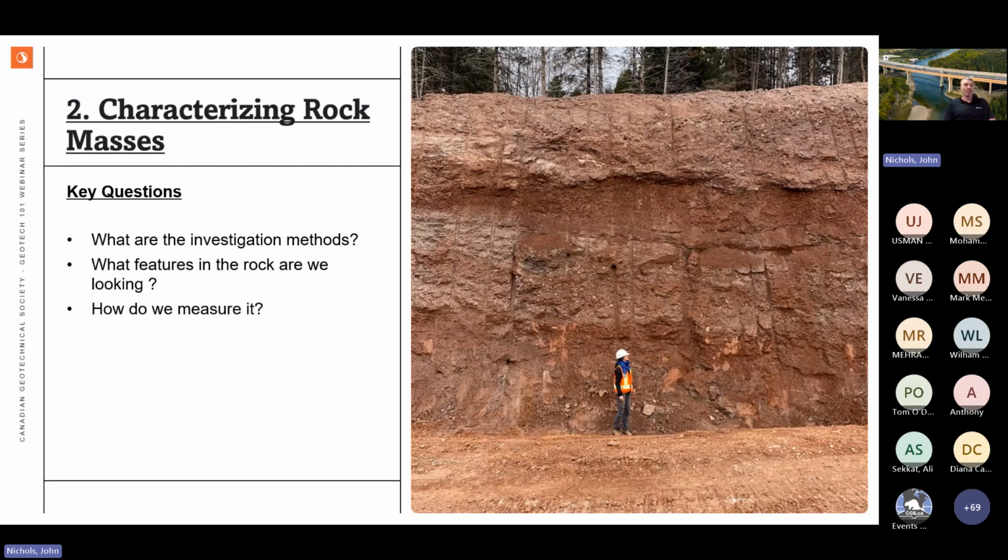This photo above here, my colleague and I visited the site, and you can see this is a silt lens. Only over time, as that eroded and the project continued, did it become a concern. Identifying this early, studying it, knowing these exist, would have avoided the pause in the project and these construction delays. It's only as it progressed and weathered that people started to take notice. So we need to understand the site. Even after it's exposed, we need to map it and further understand it.